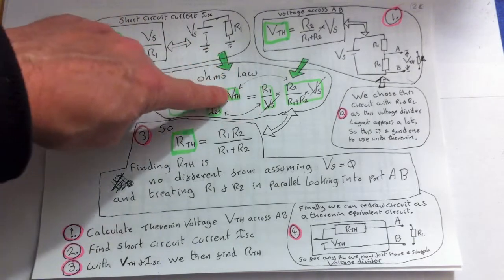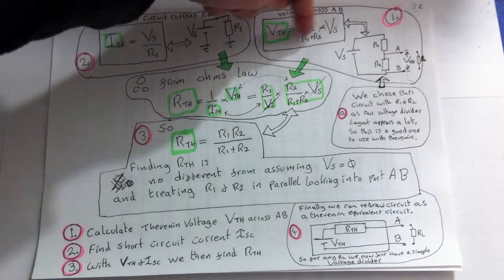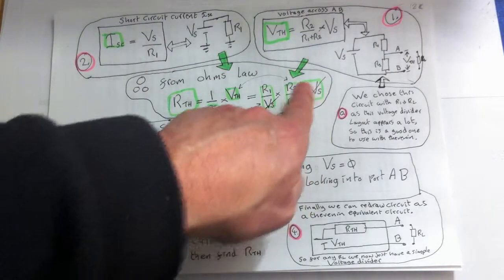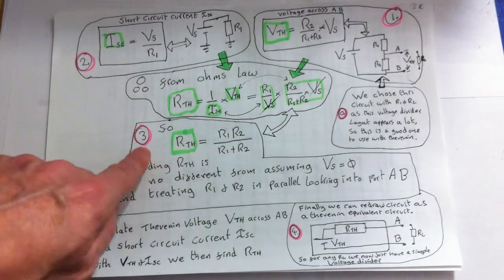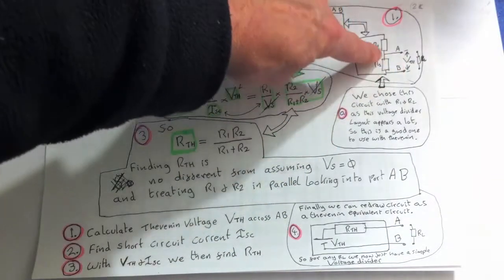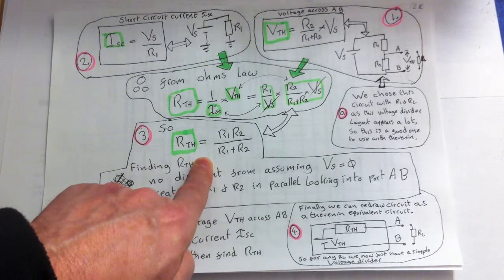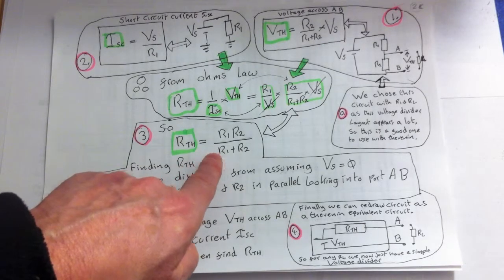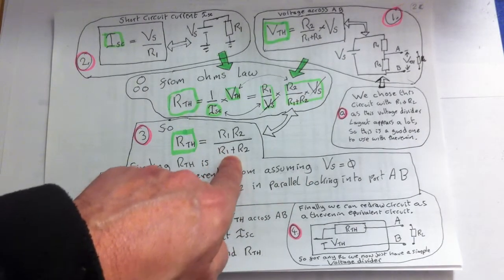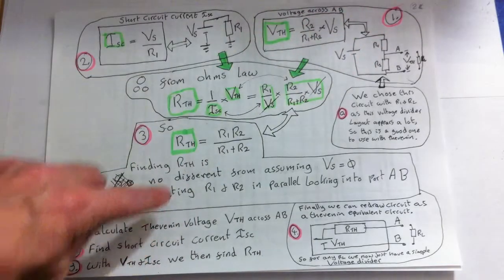Then, of course, the Thevenin voltage is the voltage divider calculation we did. So we place that there, and you can see here that the two voltage sources cancel, and we're left with a really neat solution. For this series resistance, whether you've dropped the voltage across the bottom resistor, you're left with a really nice result. Basically, after you've cancelled the voltages, you're left with R1 R2 divided by the total resistance, which is the same as calculating a parallel resistance equation here.